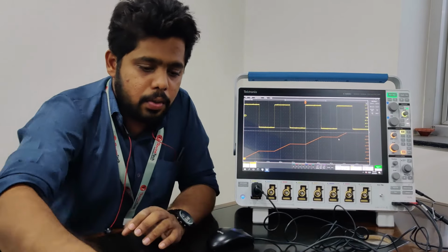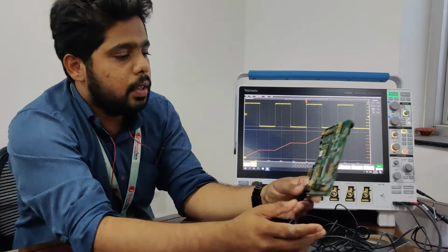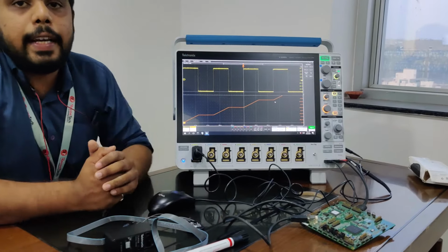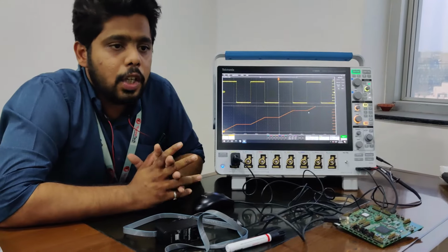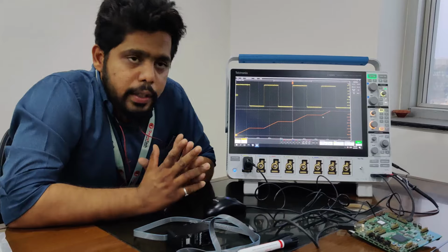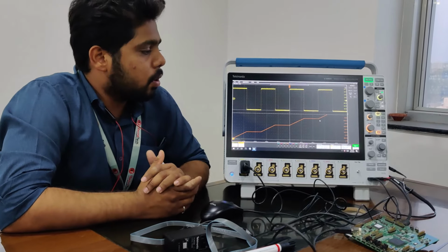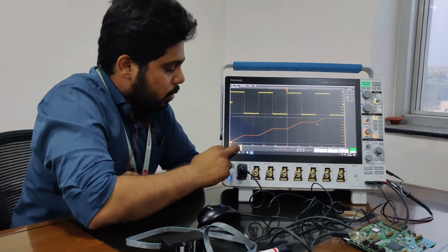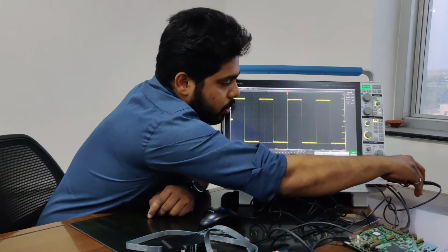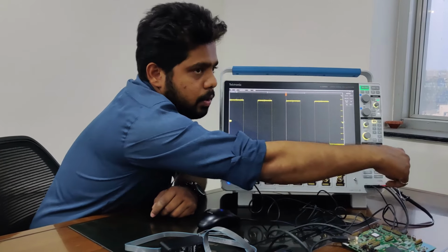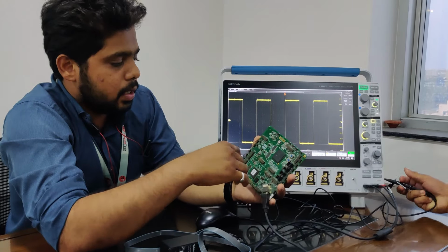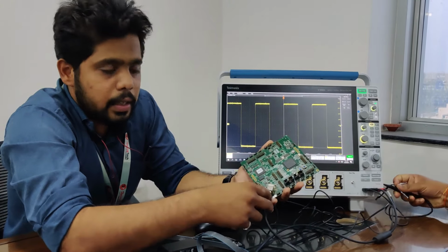Let's take an example. This is the board which we have. The oscilloscope which we are using here has a waveform capture rate of up to 5 lakh waveforms per second, and for this we have a patented technology called fast acquisition technology. I'll turn off the second channel and remove the signal from the compensation part. Can you help me remove that signal? Okay, in this board we have a few signals, like a fast occurring signal and a rarely occurring signal.